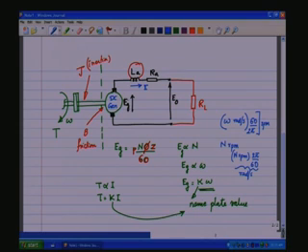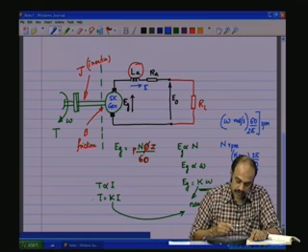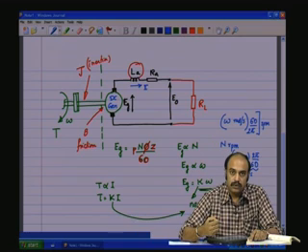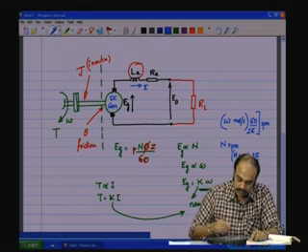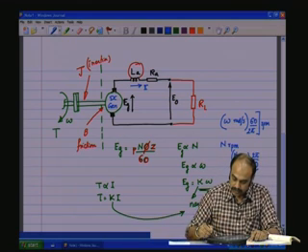Likewise, just as the EG, we said that the DC generator is a gyrator, wherein the EG, which is a potential variable on the electrical side, is linked to the flow variable on the mechanical side. Likewise, the potential variable torque on the mechanical side is linked to the load current on the electrical side. So, T is proportional to I, T is equal to K I, the same K into the load current I. So, this is basically the whole principle of the DC generator in terms of the equivalent circuit.